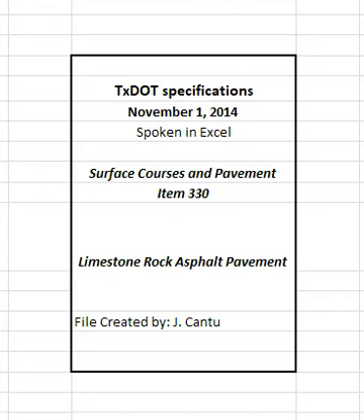4.1 Quality Control Plan, QCP. Develop a written QCP and submit for approval before beginning production. Follow the QCP in detail. Obtain approval for changes to the QCP made during the project. The engineer may suspend operations if the contractor fails to comply with the QCP. Include the following items in the QCP.